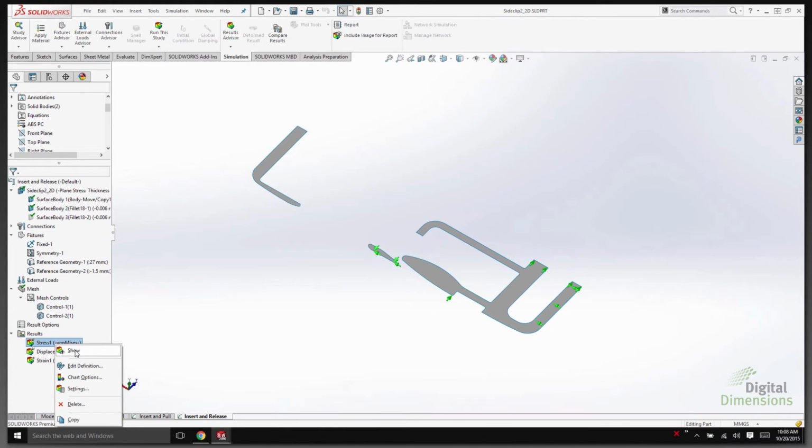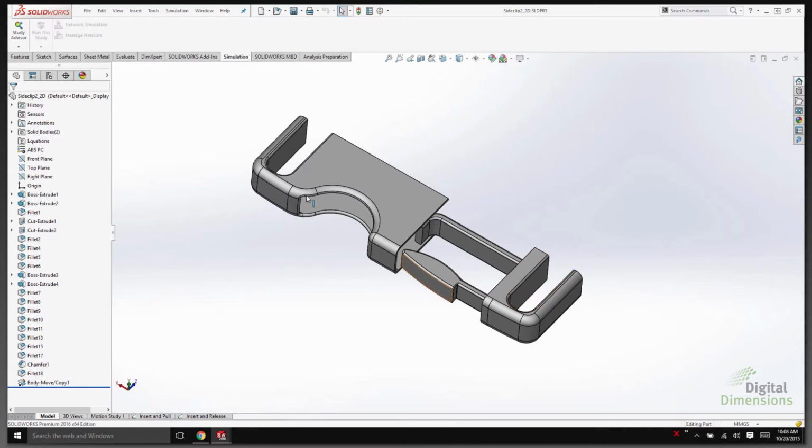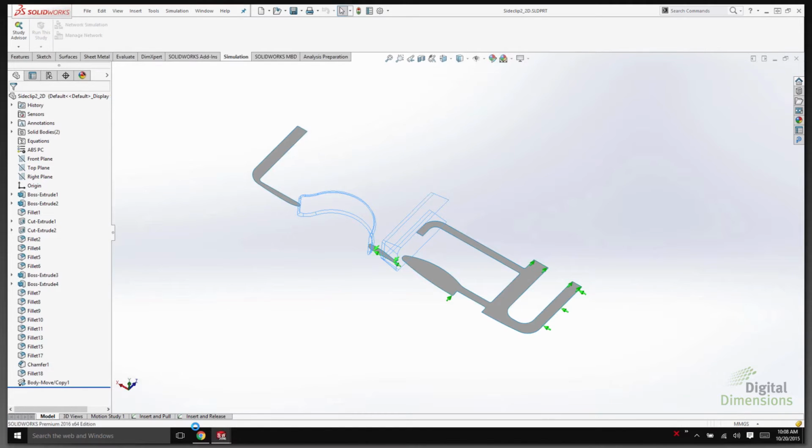So this is a clip, right? Like a backpack clip. As we push this thing together, we're going to see this thing flex in and then flex back out. And then as we pull it apart, we want to push this edge in, pull it back out. Something that may have been difficult to do in the past, as we had to manually calculate how this thing was going to push apart, or create 2 different configurations of it. Now we can do it all in a single simulation. We'll go ahead and play the result here for you.